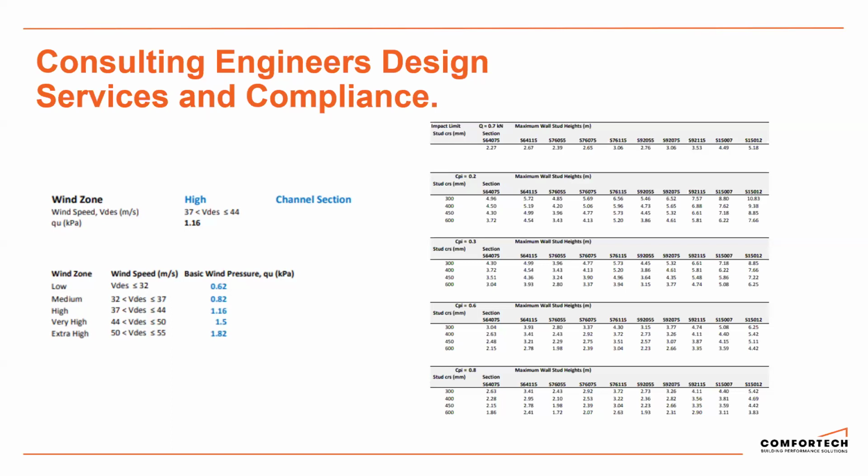Warehouses are a great example of where really high wind pressure can come in. You've got large roller doors that get opened, trucks entering and exiting buildings. That's basically a giant wind tunnel. So if you're thinking about your roof, it can deflect an awfully long way. Also your steel stud can, in terms of internal partitioning.